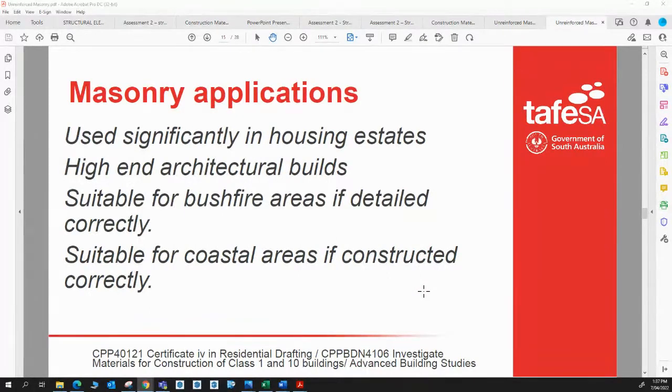Mastic is sort of akin to silicone, but it's not exactly the same. Basically, what a mastic does is the outside of it sets like a rubber, but the inside of it stays quite soft. What that means is that it bonds well to whatever it's squeezed into, but then extends significantly, so it has a high extensibility.